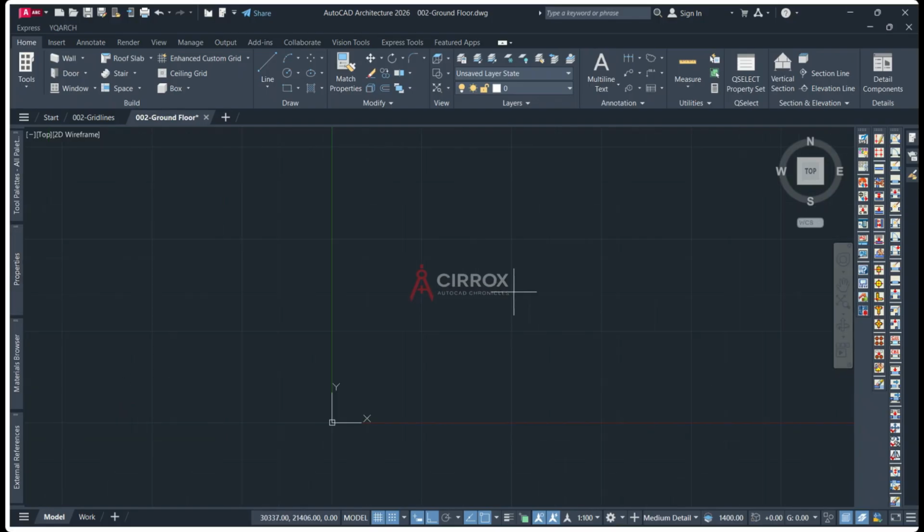My first one, I'm going to start from this side, and I'm going to give a distance of 550 in here. Enter, and I'll give another distance of 3,500. That's how it goes. Another one, 6,000, and I'm also going to move up 3,000 to 2,250,